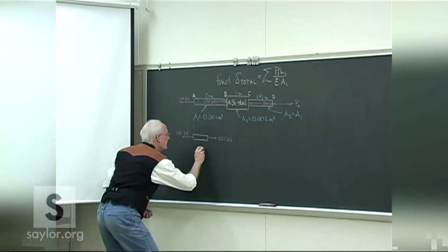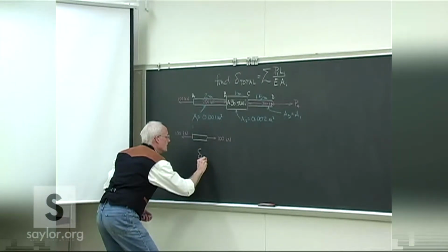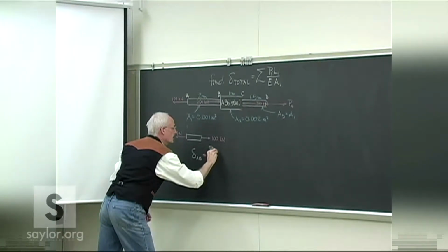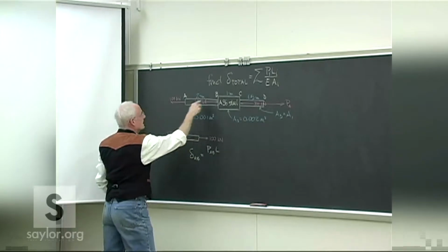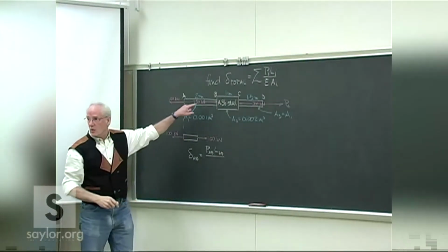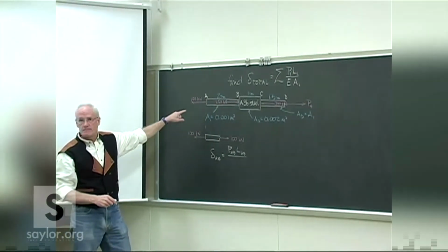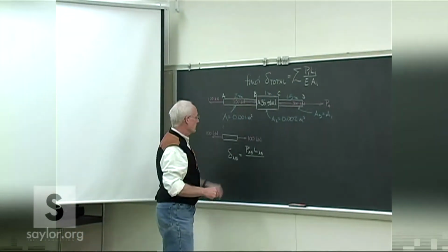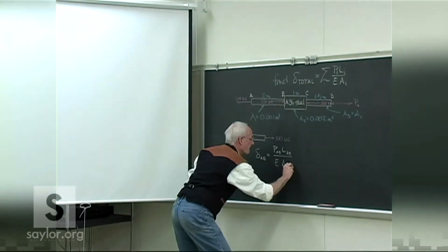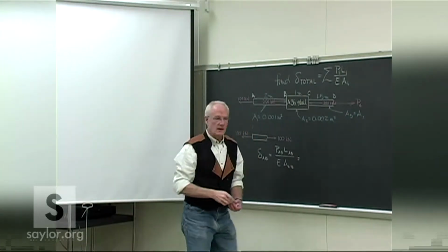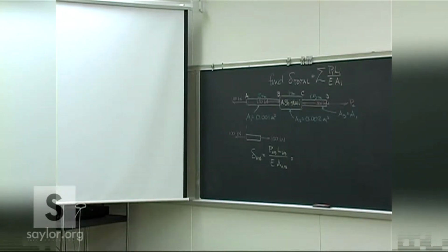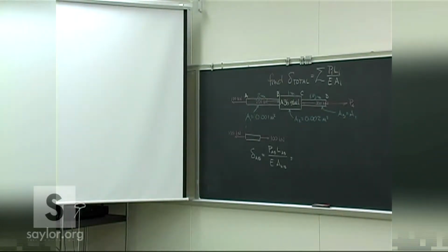So we can figure out the deformation of just that section by applying that load over the entire original length of that section. That's assuming there's no intermediate forces applied, which there aren't. There's no other force until point B. And you can figure out the individual deformation for any of the pieces. Go ahead and run down the rest of the structure from there.